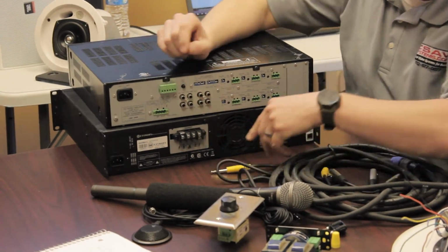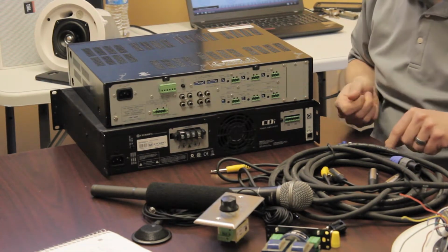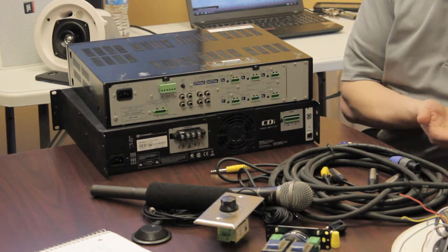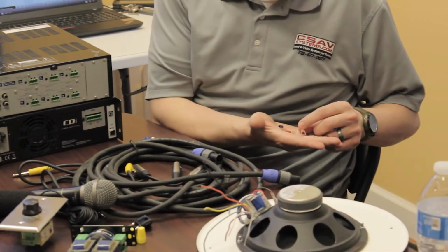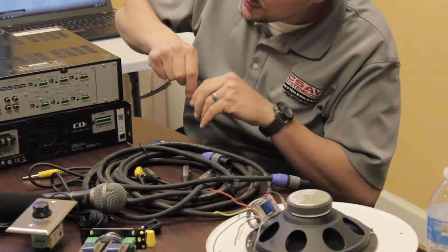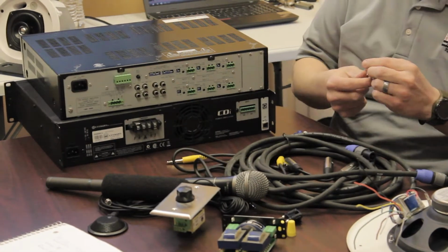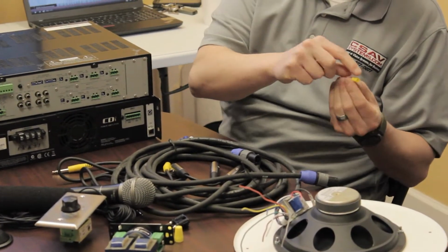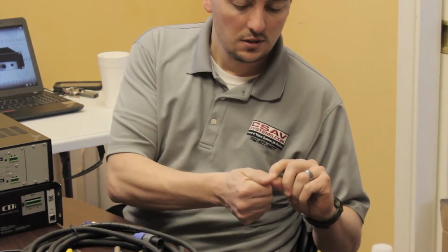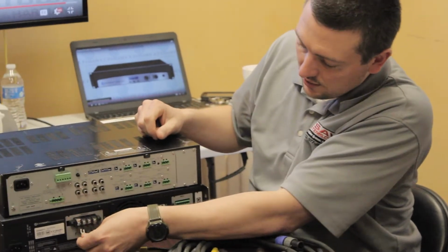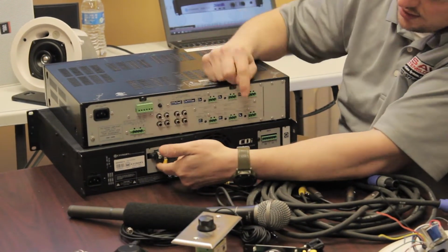Something like this, we're going to use what's called Spade Connectors. Some people call them fork connectors. They make different sizes depending on different gauge wire. So you have to judge what gauge wire you're using and see what's going to fit in the slot. So basically what you do is strip back the wire, shove it in there so the front of the wire comes out a tiny bit, crimp it down. So you've got your left and right, or channels 1 and 2, put it in under, and screw it down.